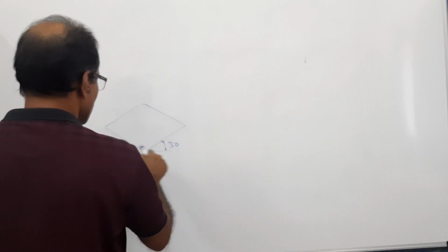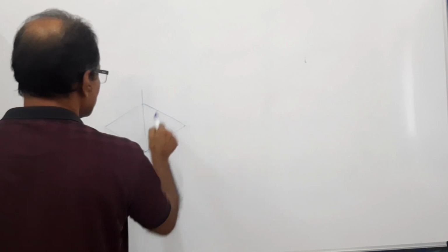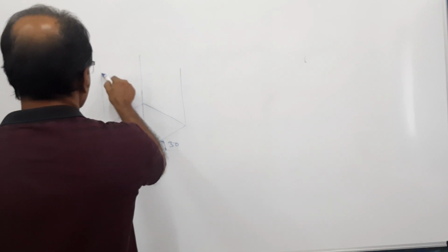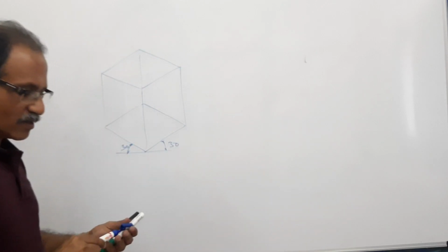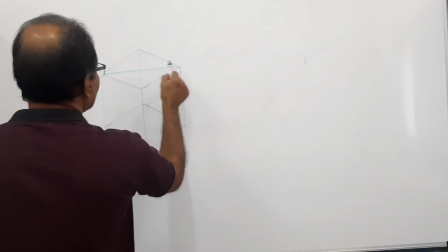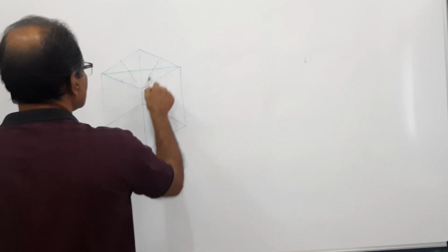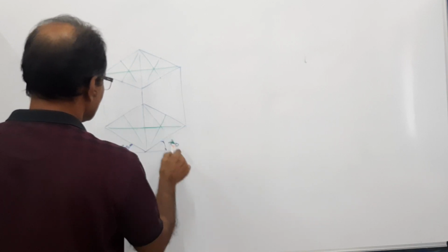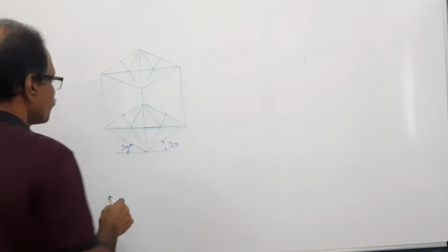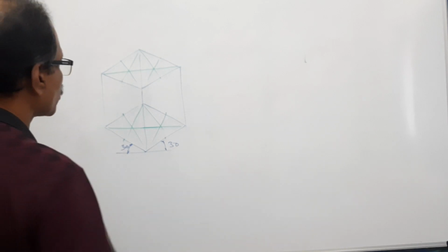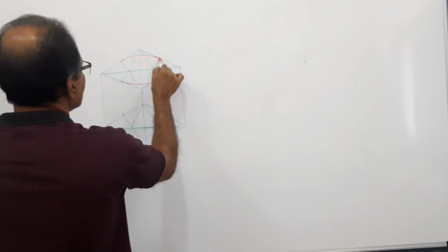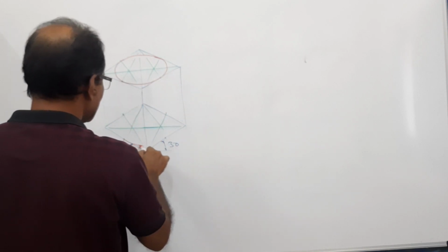30, 30. Take the height up from all the four corners. See, since it's a rhombus, a vertical line through this will pass through this. Check. What is this? It's a square box inside which the cylinder is kept. Now, join the northern diagonal, find the centers of the sides, join them to the obtuse angles. Do the same thing in the plan, in the bottom. Now what? Use the four-centered method and draw an ellipse. Use the four-centered method and draw an ellipse.